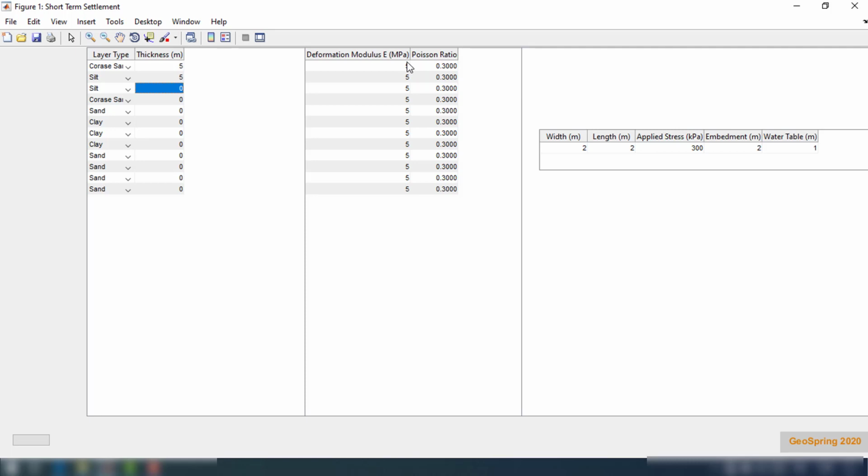Here you will insert the value of the deformation modulus. I don't like to say Young modulus, because in soils it is more interesting to talk about deformation modulus, as the Young modulus is measured without a confining pressure. So the modulus of the first layer, for example, is 10 MPa, and the silty layer will have a modulus of 25 MPa. Here we can put 0.33 and here 0.35.